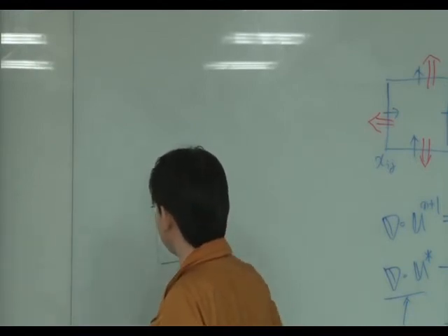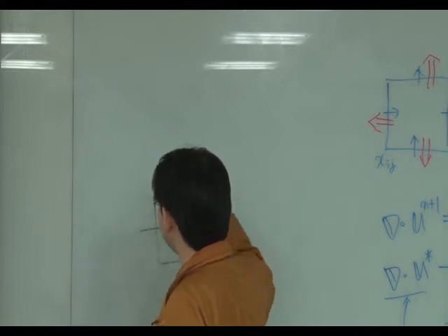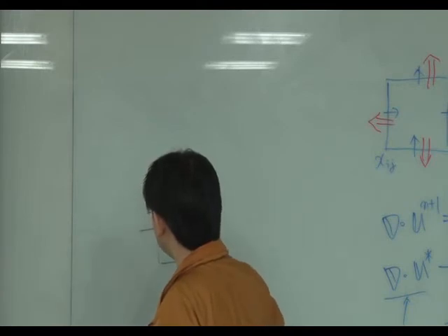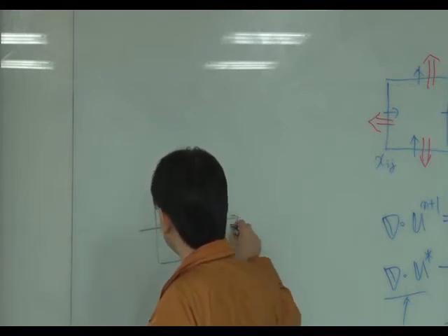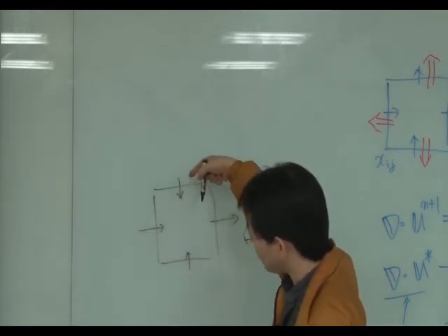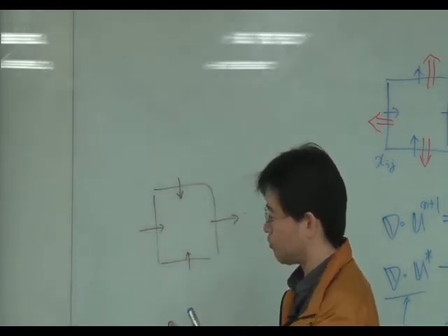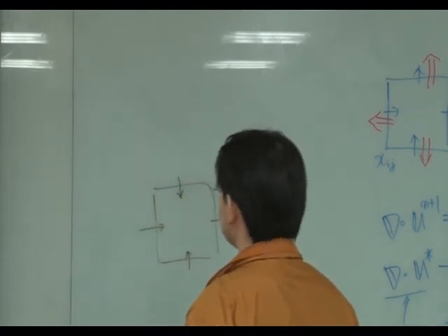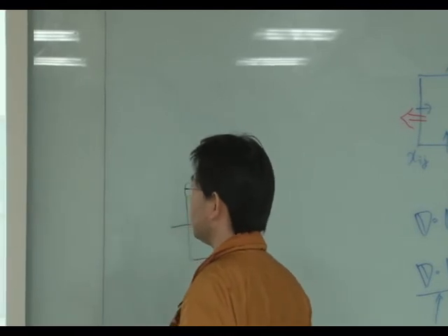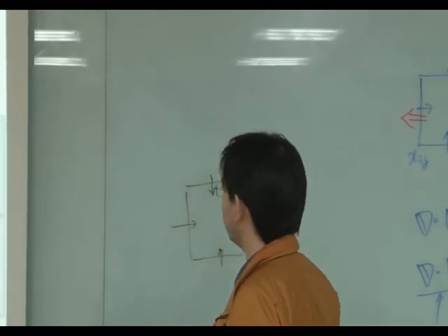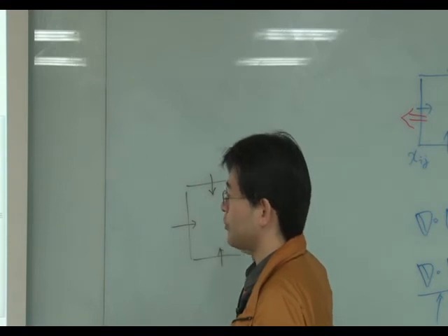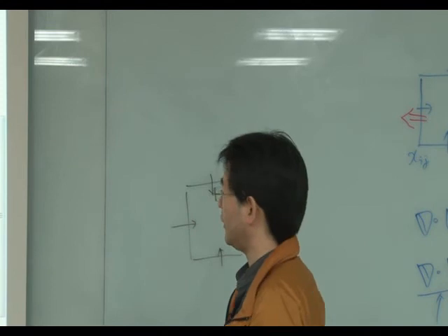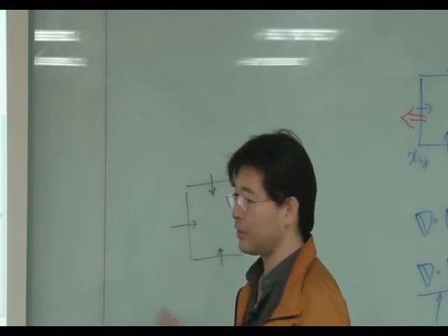The predictor velocity might not satisfy the incompressible condition, so it might be like this. In some direction, it has compression or depression. So we have to cancel this compression or depression effect provided by a predictor velocity by adding pressure gradient.